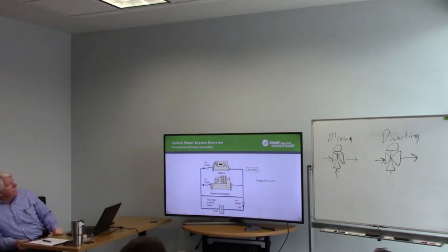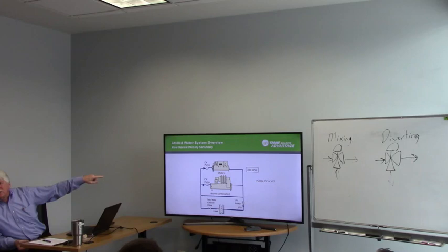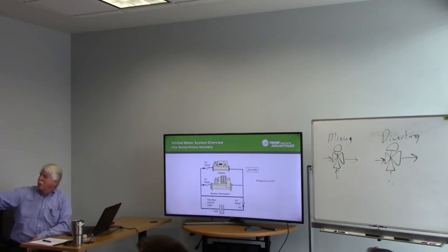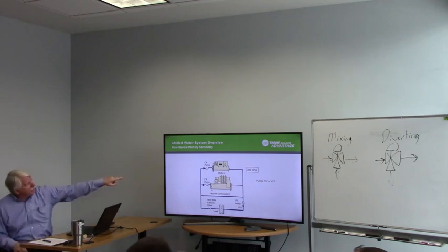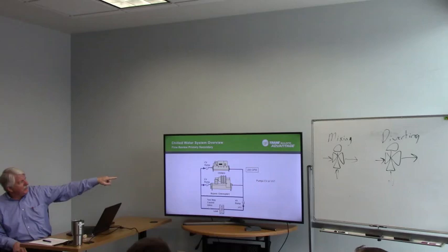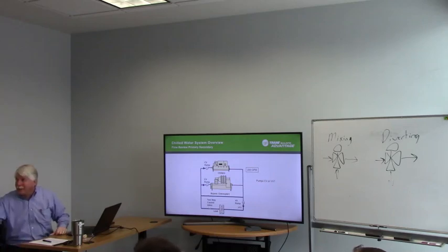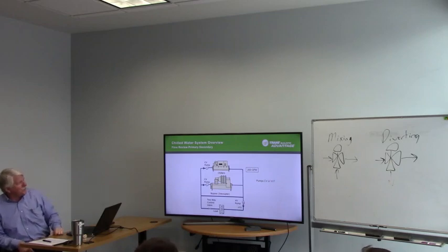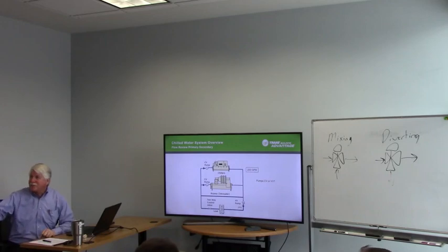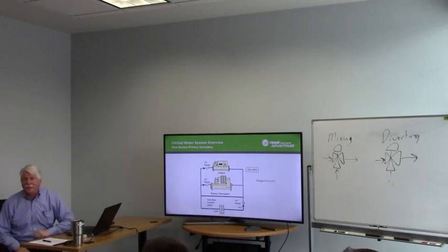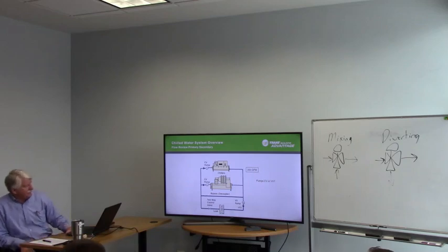Now, is the pump on the little chiller constant volume or variable volume? Here, we'll just go around the room. We'll start with you. Is the pump on the little chiller constant volume or variable volume? Constant volume. How do you know that? Because it says CV. Okay, you get the next hardest one. What's the centrifugal pump? Constant volume. Okay. What's the system pump down at the bottom? Variable volume. Okay, very good.